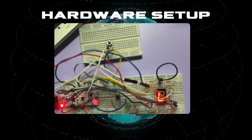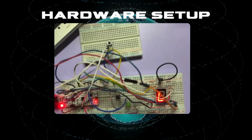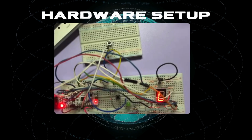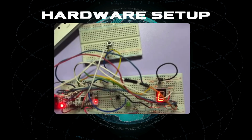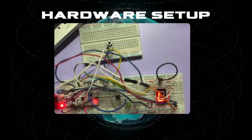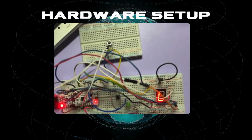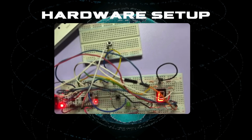So our first component is the Nucleo L432KC. Next, we use the 7-segment display, which is common anode, as output. Then we use a push button, which is our sensor. The first button is for the input, which is when a car enters the car park. And then we use a push button for the car out. And for the push buttons, we set them as active high.